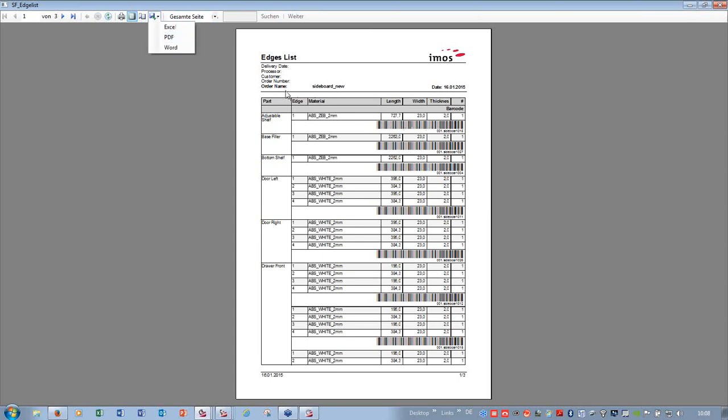If you need it in your company, we have here the order name, we have here the edging material name, and also the length, width, and thickness. And also this information is affecting the calculation later on. So if in your database it is written that the ABS 2 mm costs per meter, for example, €2, then we will calculate it 0.7277 meters by €2, and we calculated for the complete list. So we have also the calculation for all edge banding material according to your design.